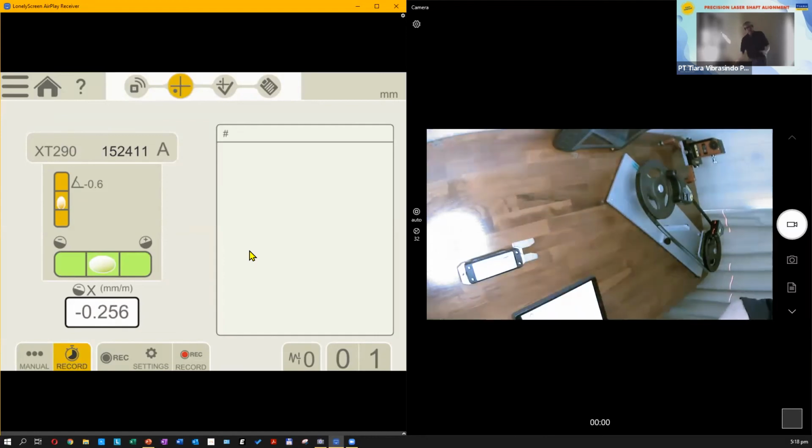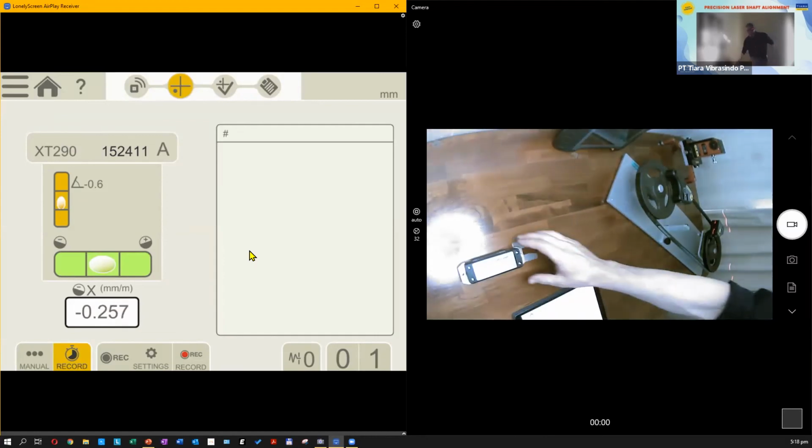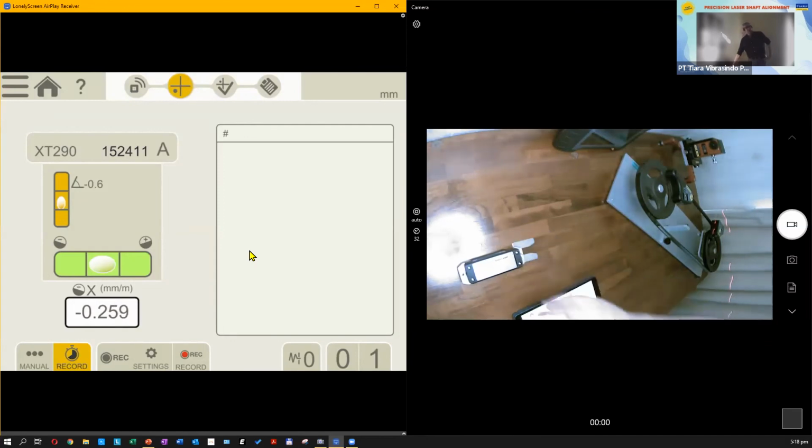So it works in ±100 degrees. There are many features. You can connect to the app 4 of those at the same time. So that can be helpful when you measure circular shapes, long distance related shapes. You'll be using the same instrument to do measurements in regards of parallelism on the vertical axis, to bring a roller, for example, into the vertically parallel same axis. And then there's a way to do that in horizontal axis as well.